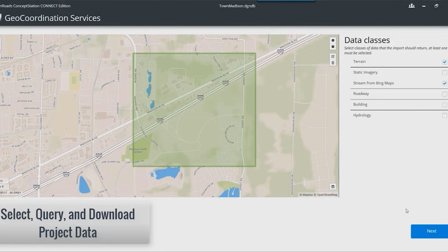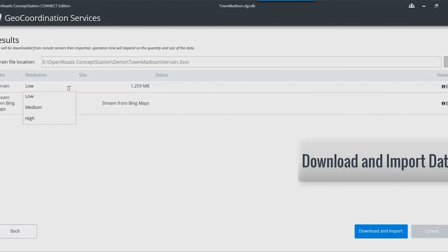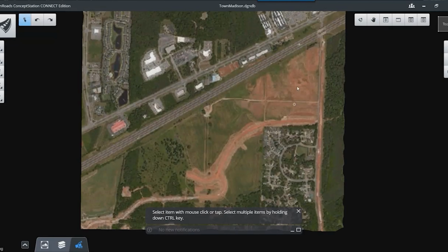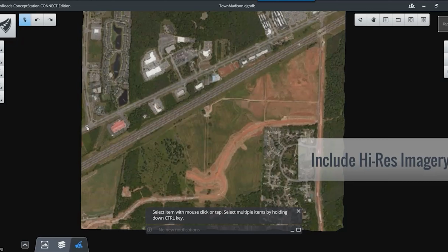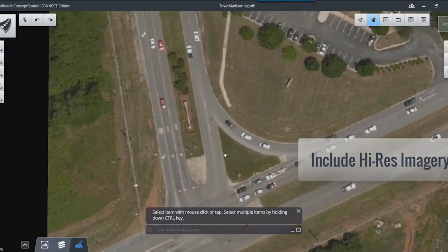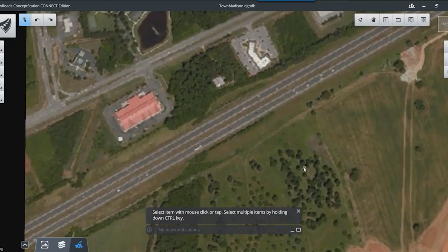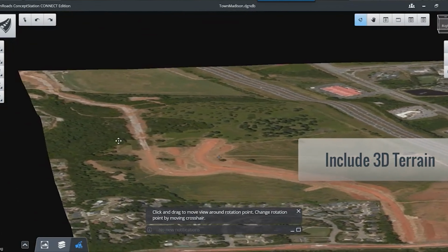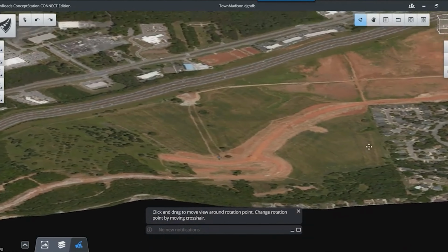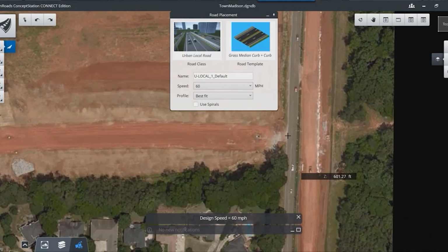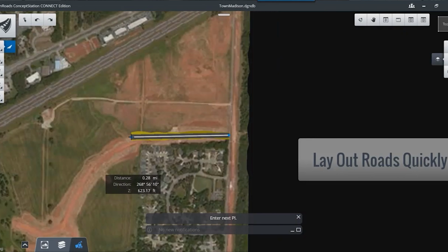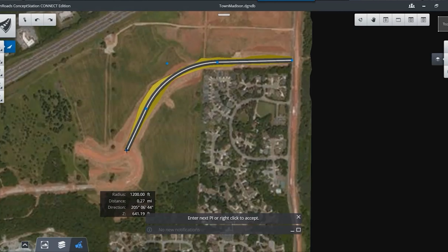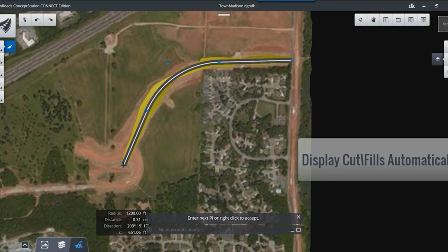Okay, so let's see an example of OpenRoads ConceptStation. So first of all, what we will do is to start the conceptual design process by locating and downloading data-rich context information for a given location to model in a real-world setting. In this way, you can import data from the GIS server included in the software to create intelligent 3D models in context with minimal effort.